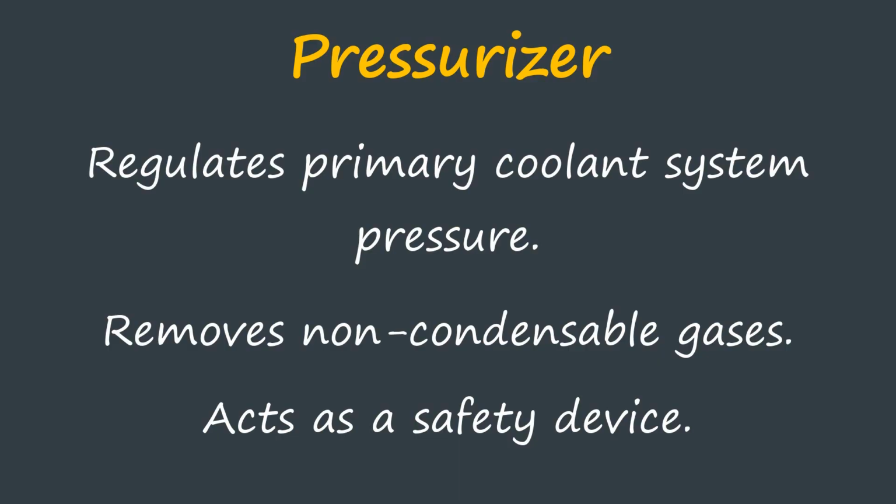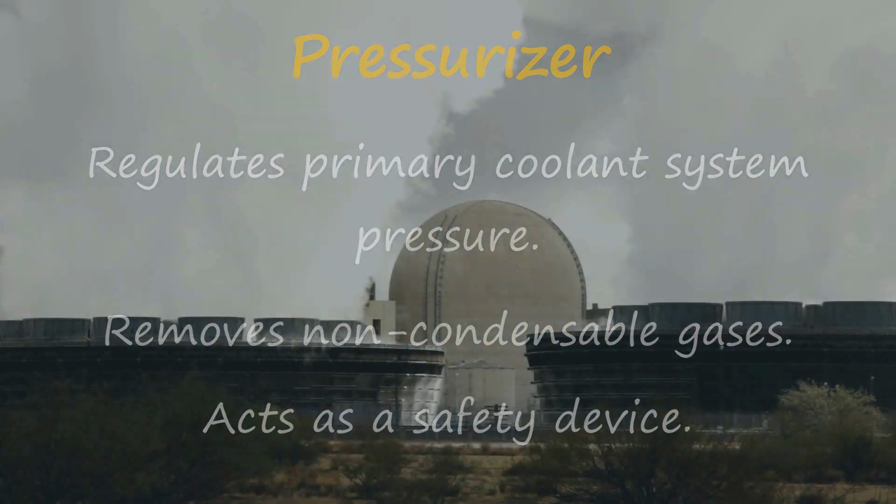It also acts as a moderator to control the fission reaction within the reactor. It's essential that the reactor remains full with primary coolant to prevent damage to all of the internal parts of the reactor. The steam generators also should be full of primary coolant so that we don't get any tube ruptures or uneven thermal loading across our tube bundles. So the pressurizer has multiple functions. It's not there just to pressurize the primary coolant loop.